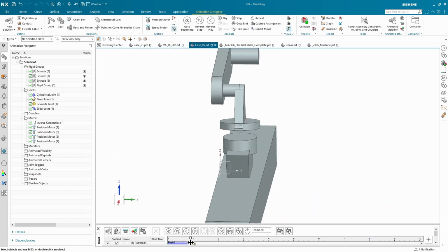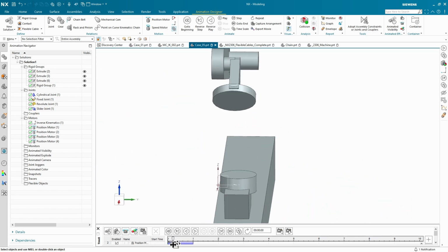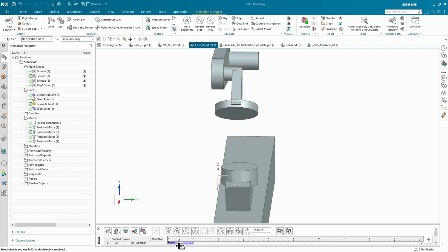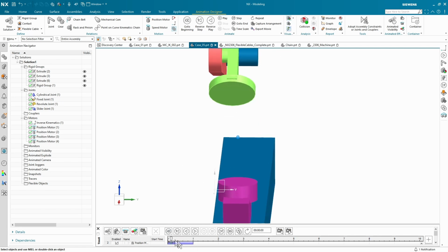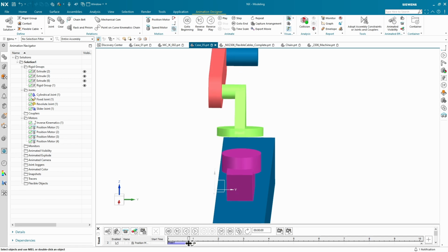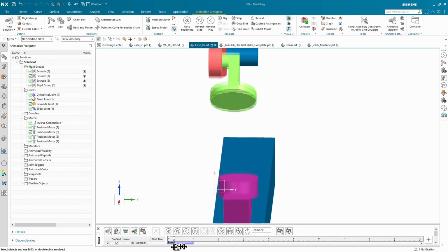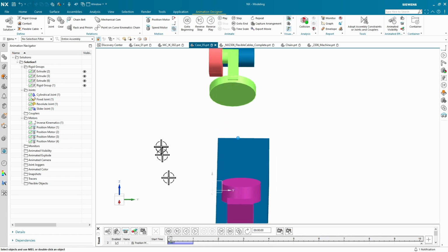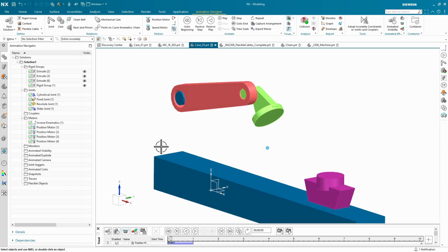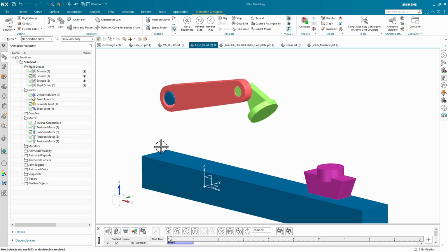Not only does the part rotate properly, but notice how it has to slide across to meet the conditions there. If you change my color on, you can see exactly what the green part is having to do, how it rotates and slides out. We did that with a cylindrical joint. Keep in mind that you may have to use different joints than you're used to in the past to allow things to solve. Inverse kinematics, whether you're using one body or two body, doesn't work on every single joint.